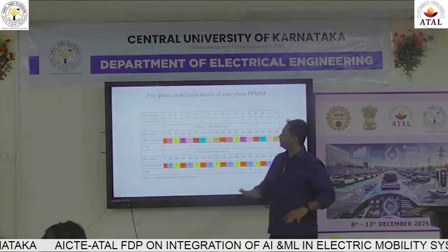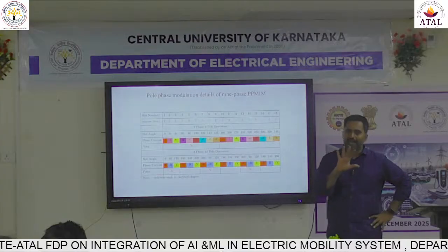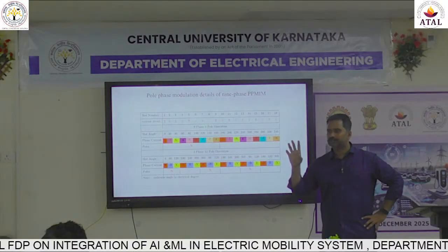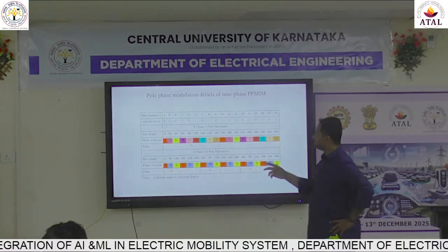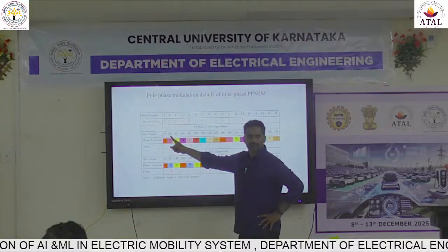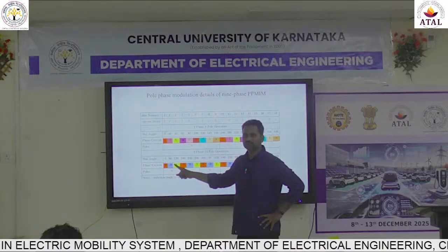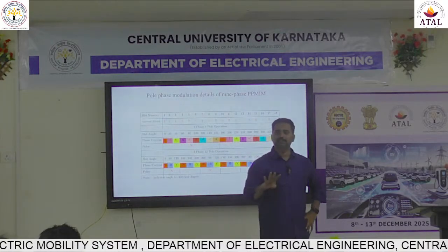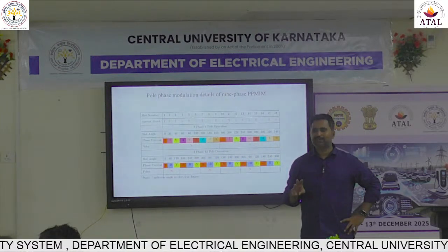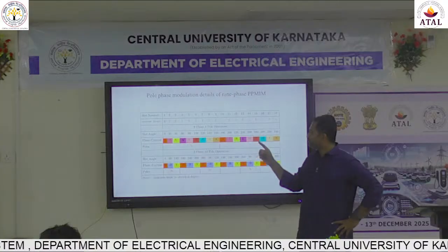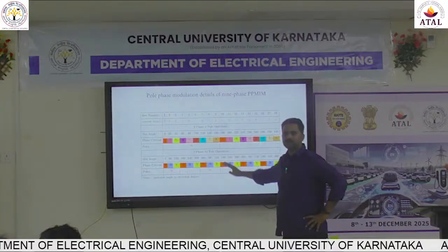If you do not understand something, it may sometimes be confusing. Just trust the angles between mechanical and electrical. There is a relation: theta electrical is equal to P by 2 times theta mechanical. Just see here, this is mechanical and this is changed by 60 degrees. What has happened? P by 2 is 3, that is, the number of poles has multiplied 3 times. So that means 4 pole becomes 12 poles.